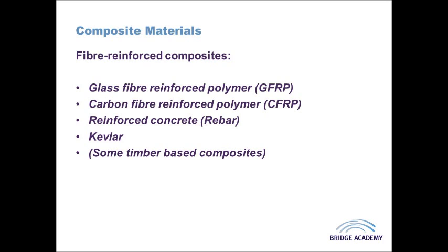Now, the advantages of these sorts of materials are the fact that we can mould them very well around various different shapes, and the polymer will hold them in place. As with polymers, which have very good strength to weight ratio generally, but are not the strongest of materials, the advantages of things like glass fibre reinforced plastic and carbon fibre reinforced plastic is that the fibres give lots more strength to the actual matrix or the polymer as such.